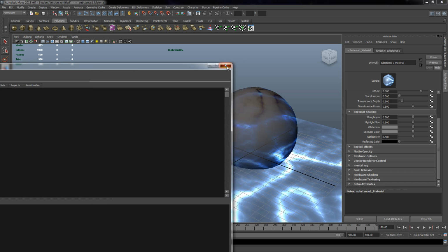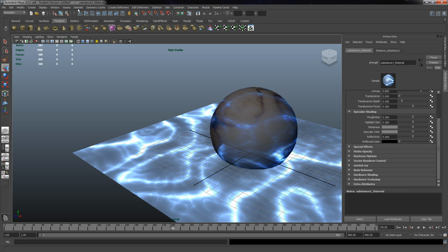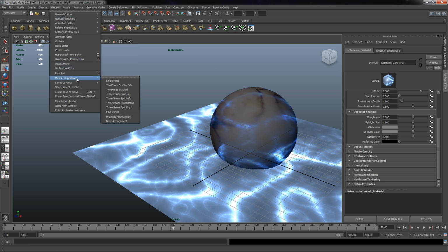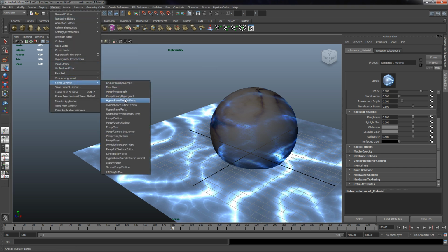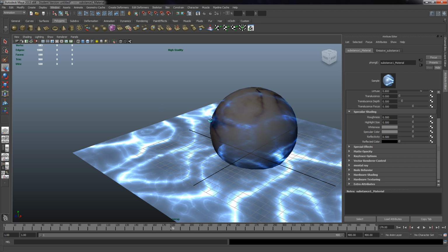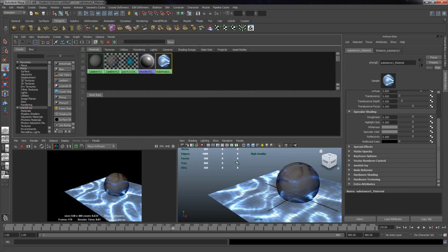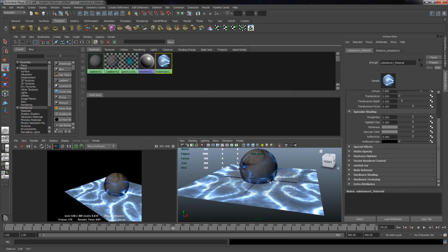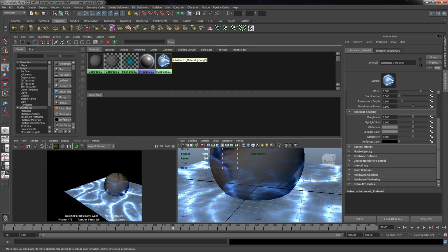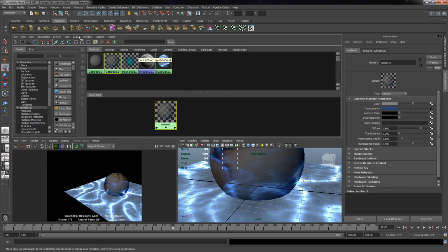Before I continue, I'm just actually going to switch my view to have a much more natural view for this. So just switch to Hypershade / render / perspective, because we're going to be using all three of those, and I think it's a better arrangement. Cool. So anyway, that clearly didn't work. If you can't find where your material went, just drag it into the work area and click it, and then hit Graph Input and Output Connections. That'll show you pretty much everything you need.